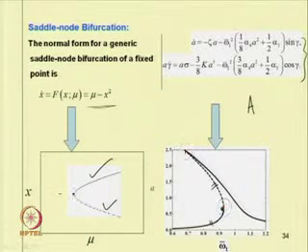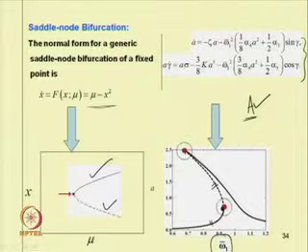One can see the slope at this point is the same for both the stable and unstable branch, so this point is a saddle node bifurcation point. In this case, by finding A, the Jacobian matrix, find the eigenvalue, and check at what point, by changing this control parameter, the eigenvalue changes from positive to negative or negative to positive, or it has a 0 eigenvalue.